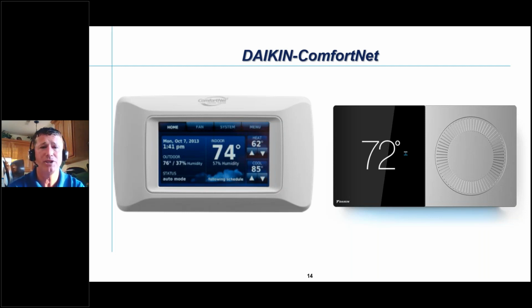We've had some different generations of them, but when we're talking about communicating thermostats, we're now talking about thermostats that are not using switches. We're talking about thermostats that are using variable voltages, and every manufacturer has their own type of communicating thermostat that is a variable voltage thermostat.